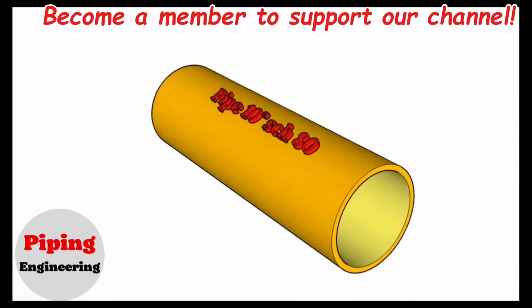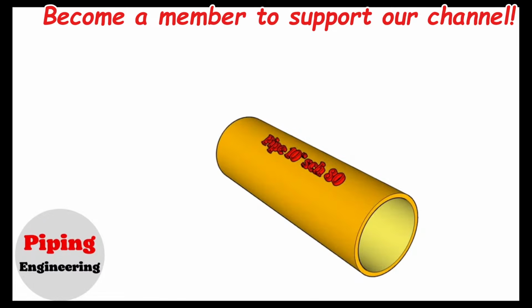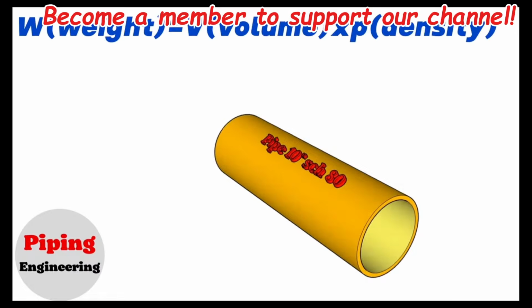The formula for finding the weight of the pipe is as follows. Weight equals volume multiplied by the density of the material of the pipe. In this formula, the density of the material is taken from the density chart of the materials. We have to calculate the volume ourselves.